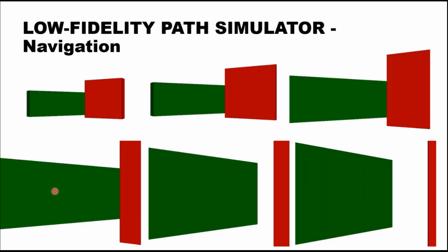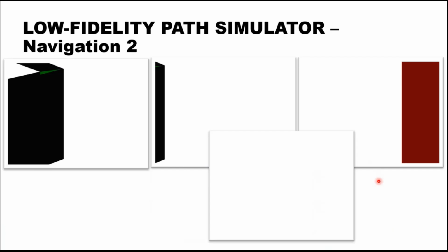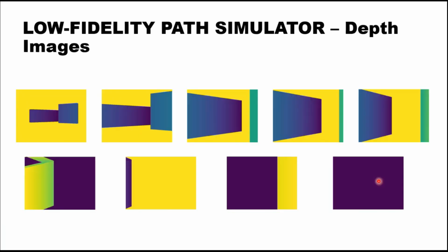Then the local planner, as we're going to explain soon, figures out there's this space here, and it starts to take a turn right in order to get past the two obstacles. Of course, this depends on the depth image. Basically, it takes the depth image, and this 2D image is converted into a 3D point cloud, where each point has the value of the distance between the drone and the obstacle.